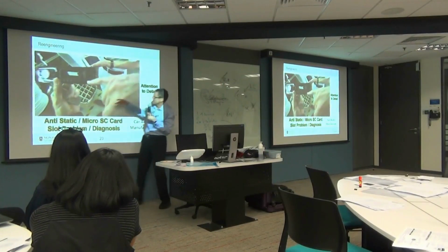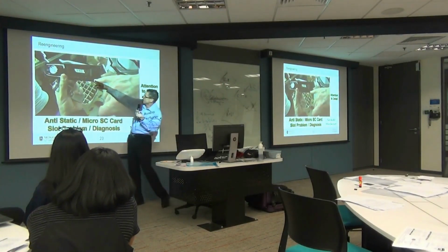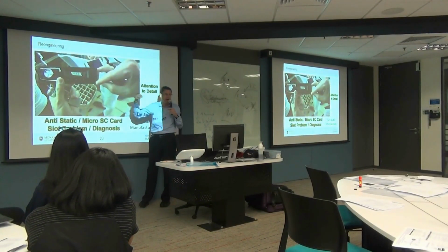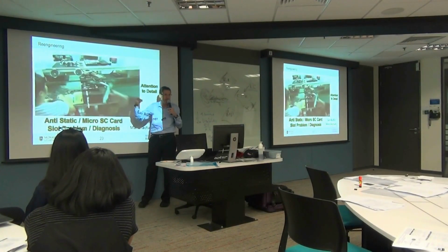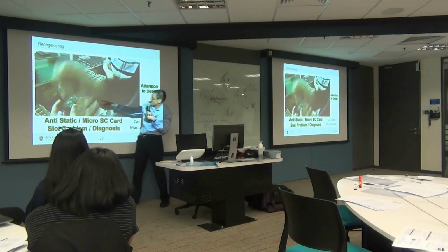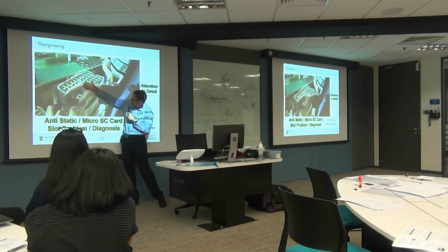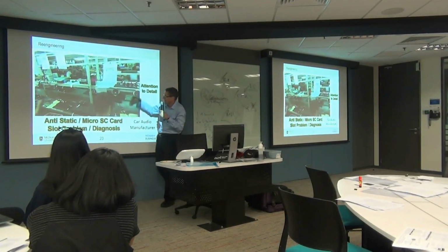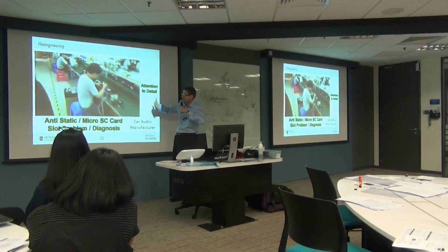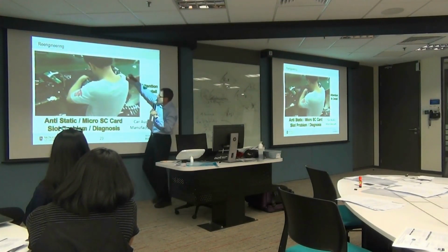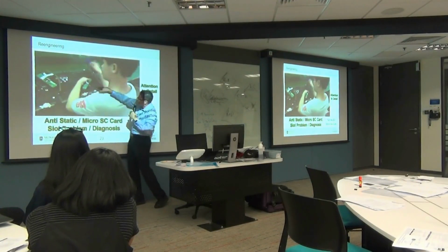That's a major problem. So we go back and we find, okay, that's the slot where it goes in, but when it goes in, it's not registering electronically when they test the SD card, when you put it into the unit. And so at the back end, it's screwed into there, it's not lined up, so we've got to go and have a look at the part where they're actually doing the screwing to see how stable that process is. So now we go and have a look at the person that's actually with the screwdriver and then screwing down.